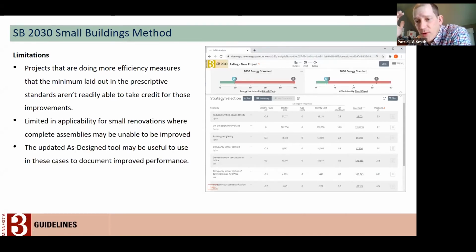We're taking a worst case scenario approach when we did our modeling evaluation of the comparison between these prescriptive approaches and the 2030 target. So project teams, even if they're under this 20,000 square foot threshold, might still select a model to take credit for, if you're ground coupling your building or doing a more aggressive energy conservation measure, because that will let you take credit for that, and that will lower your need to either implement renewables or procure renewable energy.